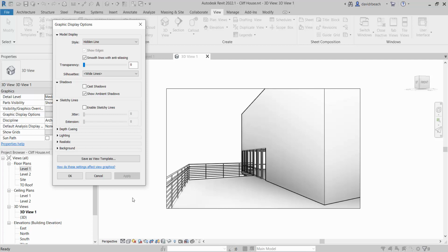In particular though, this is a tool when you're working professionally with clients. Really appreciate this based on where you're at in progress. Showing this as a drawing starts to look finished, right? And what that means to a client is I no longer have input. I can't ask questions. It's a subconscious thing. Trust me, you'll see it happen. But if I just turn sketchy lines on, so I'm going to hit enable sketchy, and usually 2-4 work really well for me, and do this, all of a sudden all the drawing edges are fuzzy. It looks like it's hand drawn, and a client's much more willing to talk with me about it.